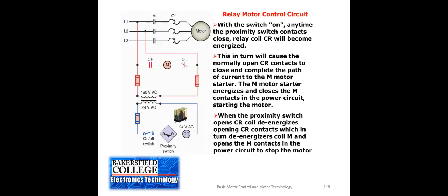There are other kinds of contactors that use a solenoid, and then the relay contacts are off to the side and there's mechanical movement between them. In a future lecture, we're going to get more into the makeup of relays and the types and the applications. In this case, we're just looking at relays as a device. In this case, we're using a proximity switch to energize a control relay. When the control relay is energized, then the motor will operate. That turns on the motor starter.